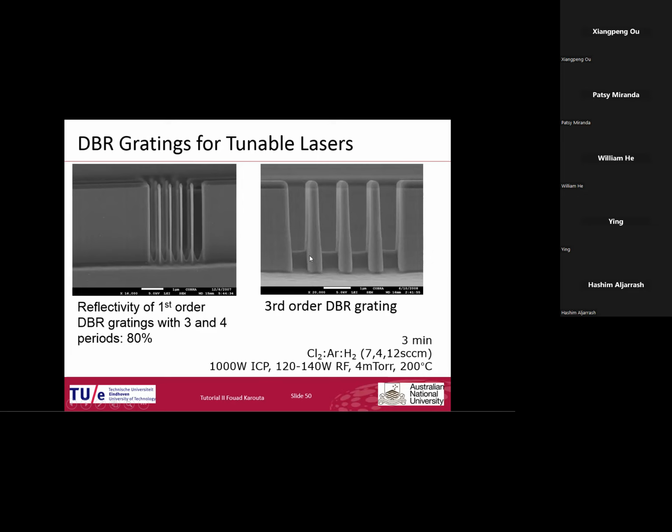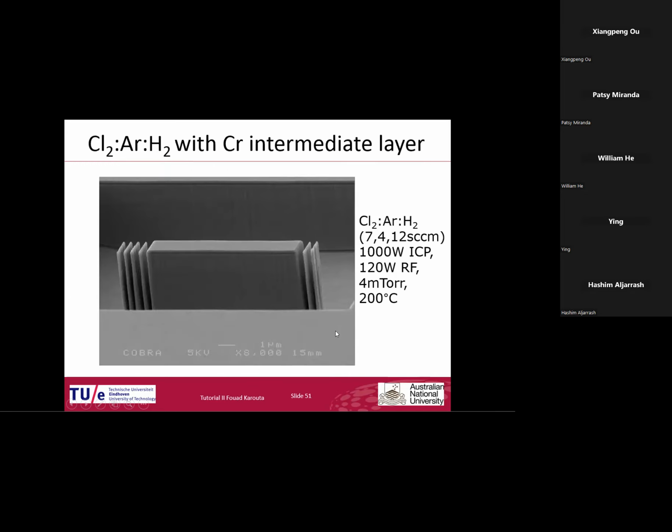Especially you see here that in the middle of the waveguide, you still have a small part of the material remaining. These were the parameters of the ICP etching if people are interested. Again, I was using heatsink paste and 200 degrees. And that is a picture from the etched area where the device would be at the end.